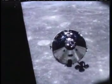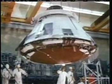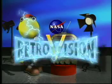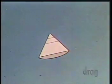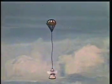The Apollo capsules used to bring the astronauts back to Earth after their trips to the moon were designed as blunt bodies. This is because this particular shape has high drag, a force that slows an object down. The blunt body creates the drag needed to deploy the drogue parachute, followed by the main parachutes. The force of drag then gently lowers the vehicle safely to the Earth.